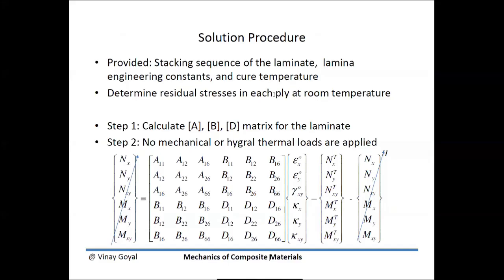So obviously, because I cured it at a hotter temperature, when I cool it down to room temperature, residual stresses will appear. The first step is to calculate the ABD matrices for the whole laminate. So you get the whole thing. There's no hygrothermal effects here, so don't worry about that. There's no mechanical load in this case, so you can ignore that.